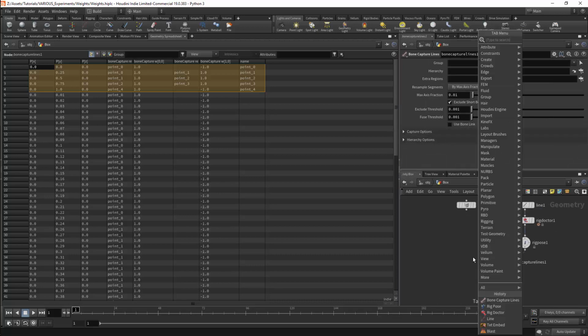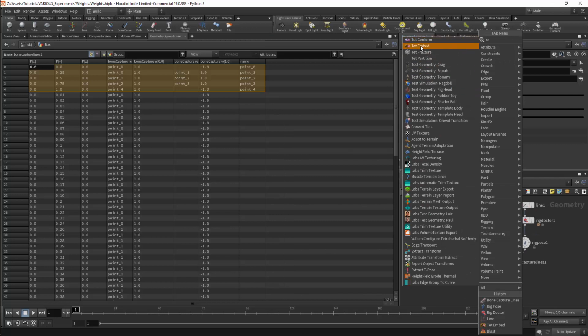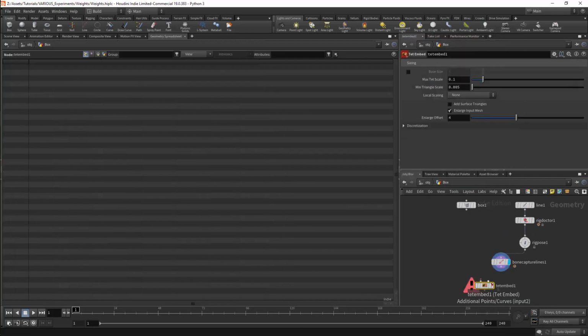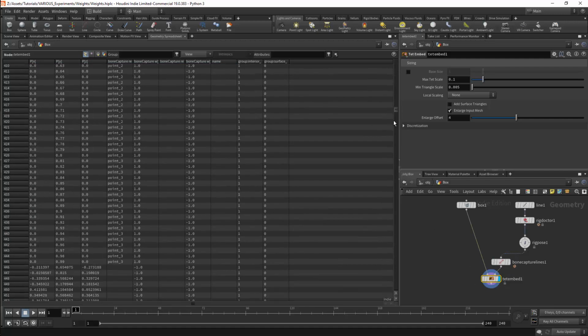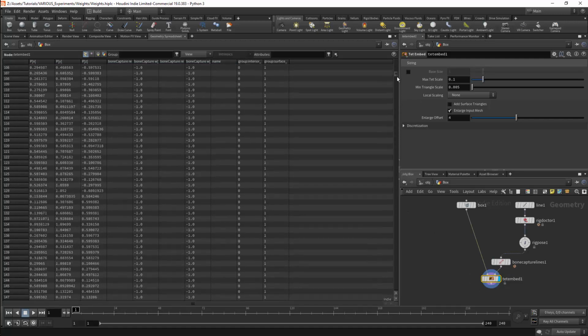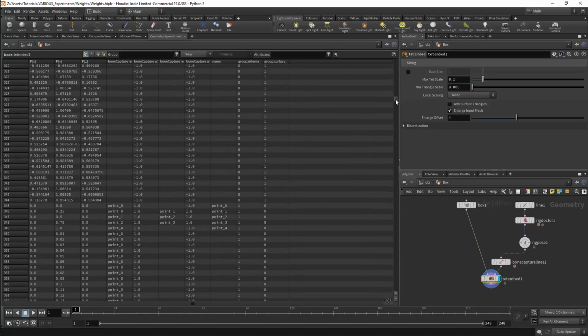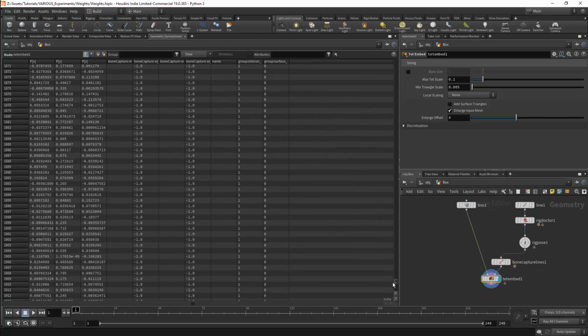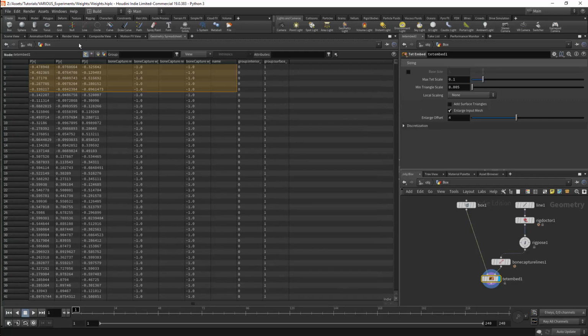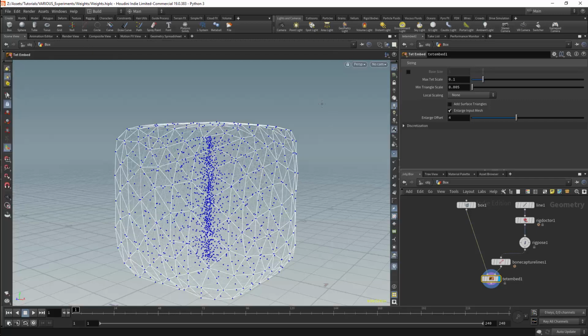The next node that we're using will be the embed node. This node will have the first input set by the mesh. The second input will be set by the bone capture lines node. This node will create volumetric 3D geometry based off the mesh, and it will propagate the bone capture data throughout the mesh. This node will not calculate any of the information, but it will be important for allowing for more accurate weights. We can return to the scene view.